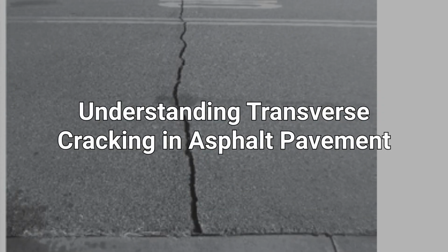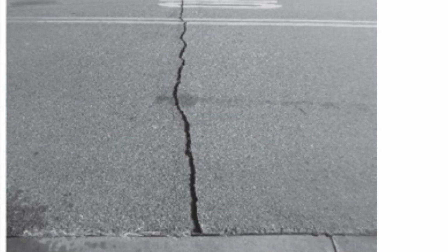Understanding transverse cracking in asphalt pavement. Transverse top-down surface cracking, also known as transverse cracking or thermal cracking, of asphalt pavement is one of the important distresses especially observed in cold regions. Thermal cracking consists of two types, namely thermal fatigue cracking and low-temperature cracking. Repetitive thermal cycles may cause thermal fatigue cracking, even though the amplitude of the temperature cycle is not so severe. A single cooling due to extreme cold temperature or a high rate of cooling may cause low-temperature cracking (AASHTO, 2015). Low-temperature cracking occurs when the induced tensile stress exceeds the tensile strength of the asphalt concrete.